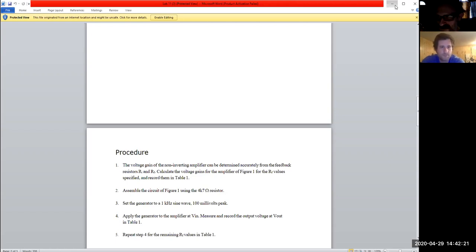All right, so here's your trick. You get what they call low melt solder. It has a lower melting point than your traditional stuff. So you take the low melt solder, so that way it heats up fast and you can spread it around and keep it heated. You get all four points, all four sides, heated up.